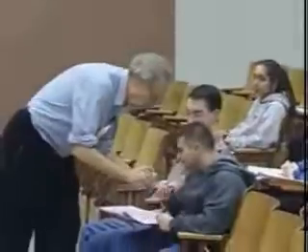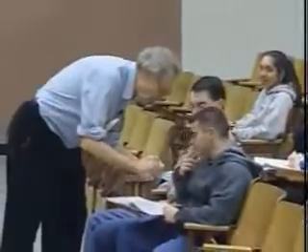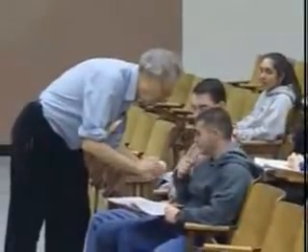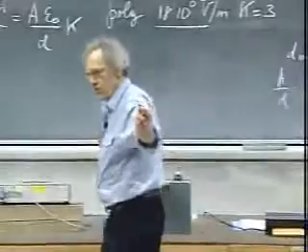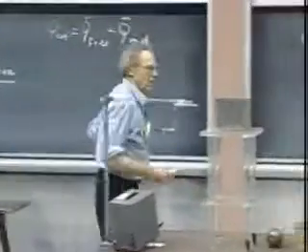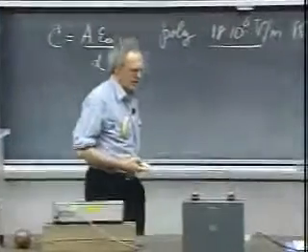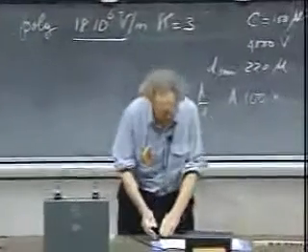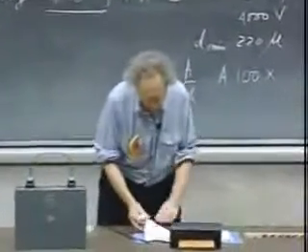Could you tell me what it says here? 100 microfarad, how many volts? 40. 40 volts. That's small, compared to this one, which can handle 4,000 volts, but the capacitance is the same. So you see now the connection with area and with thickness, by no means trivial.